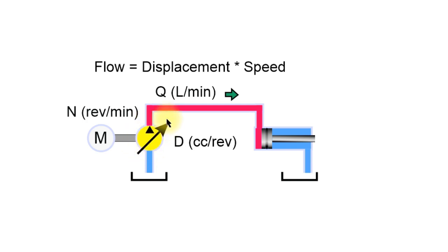To be honest, it's very common to have variable displacement pumps, either pressure compensated or load sensing, and the system takes the flow it needs and sends a signal back to these, either in pressure or pressure drop signals, and it tells it to increase or decrease the displacement. So the pump is adjusting all the time to give the required flow, but the control and the demand is coming from the system. So that's quite common, but again, not the way the fluid is controlled.